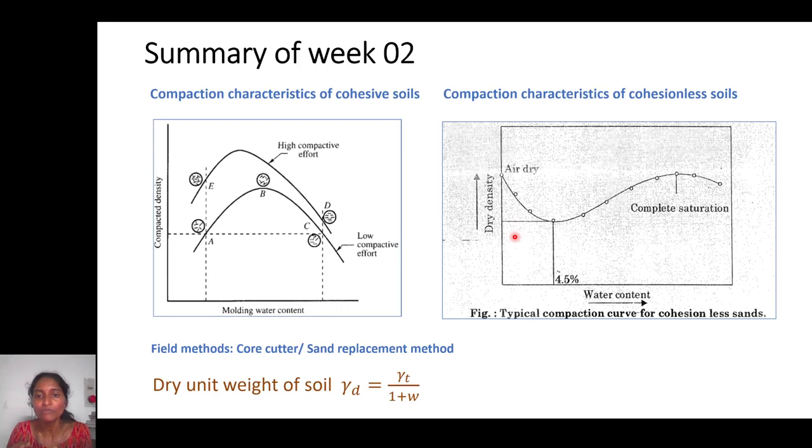Usually, when do we say any material is a higher dense material? If they all are completely settled and compact. But here, because of capillary action, all the sand is about to move to the top because water always tries to move to the top. Because of that, dry density decreases, decreases, decreases, but it will not decrease forever. There will be a condition, usually between 4 to 5% of water content, where there is a least dry density. Beyond that, if you start adding water, the capillary tubes or capillary air voids that have formed, their meniscus will be broken because you are adding more water.